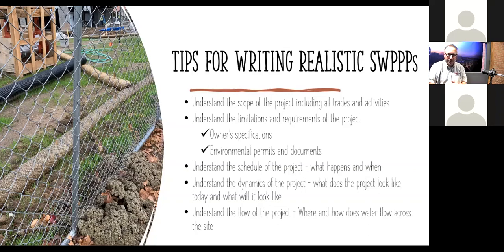For example, if they're doing in-water work or levee work or something like that, they probably have a 401 water quality certification, a 404 U.S. Army Corps permit, and probably a Section 1600 or Department of Fish and Wildlife lake or stream bed alteration agreement. And in those documents, in those permits, many times will be restrictions about when you can do activities and what type of vegetation you're going to install.